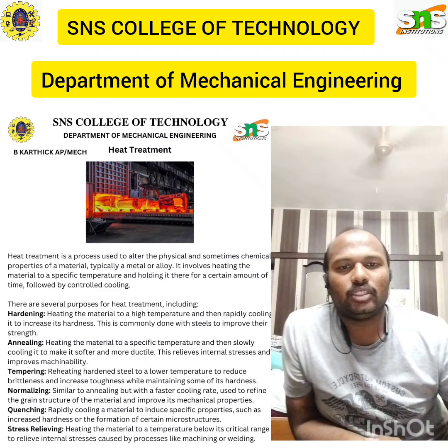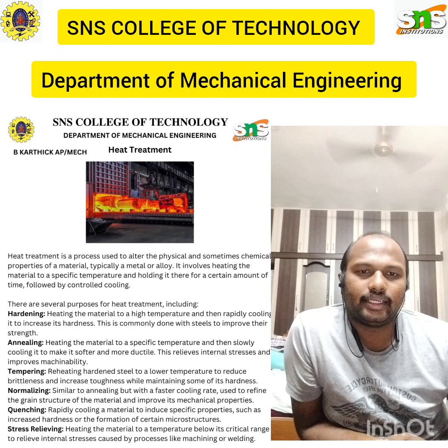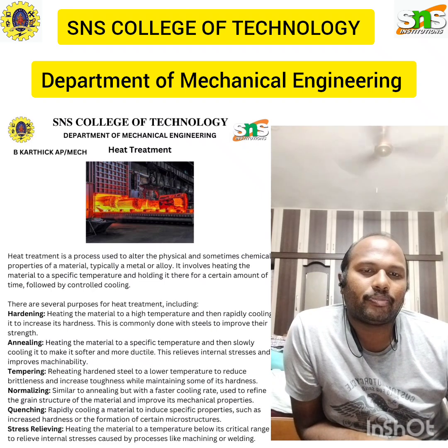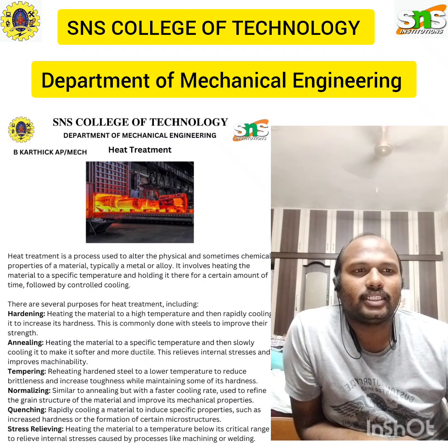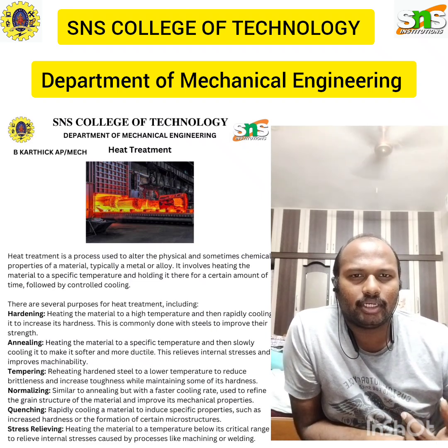So the first one is annealing, where, as I already said, we heat the material inside the furnace, and the cooling is very slow, which makes the material softer and more ductile, as well as relieves the internal stress and improves machinability. We'll see the different types of heat treatment in upcoming videos.